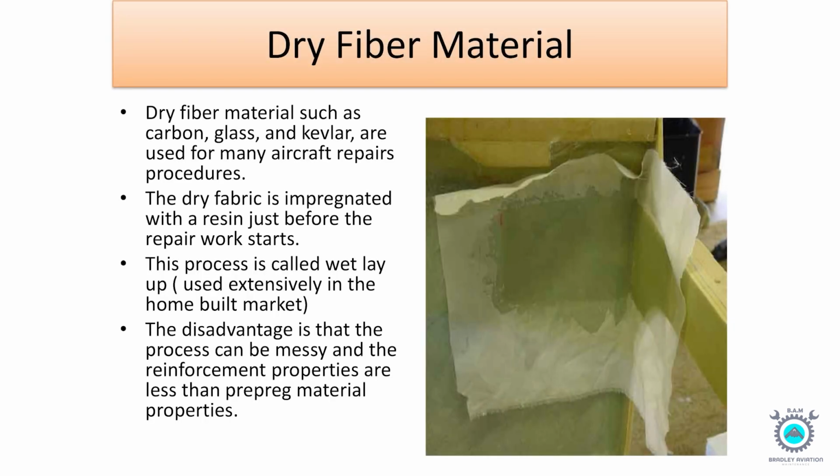Dry fiber material. Dry fiber materials such as carbon, glass, and Kevlar are used for many aircraft repair procedures. The dry fabric is impregnated with a resin just before the repair work starts. This process is called wet layup, used extensively in the home-built market. The disadvantage is that the process can be messy and the reinforcement properties are less than prepreg material properties.